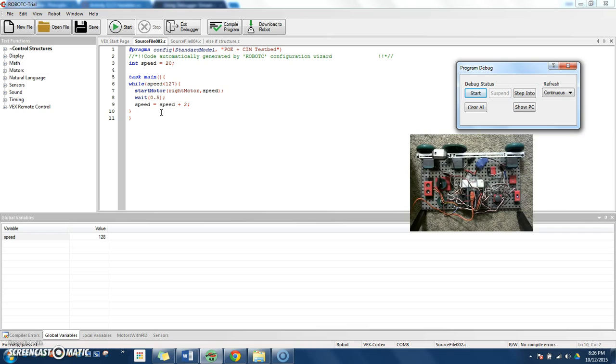A lot of people like to use servo motors for bins on their material sorter. So as your material sorter is working, you might have a servo bring a new bin around and drop a marble into it. Well, servos run very fast, so a variable would actually be a very, very easy way to control the speed, and I'm putting air quotes, speed of a servo, because you can't really control the speed, but you could have the servo tick up to a certain servo position very slowly, so your servo is not just sloshing around and throwing marbles out of its bins, which is something that very commonly happens.